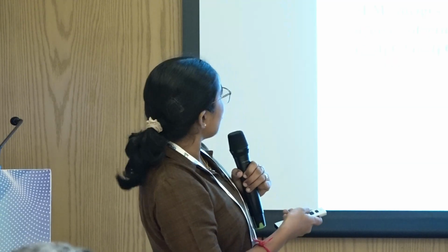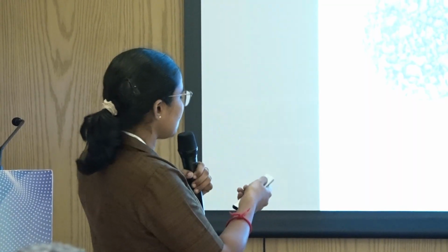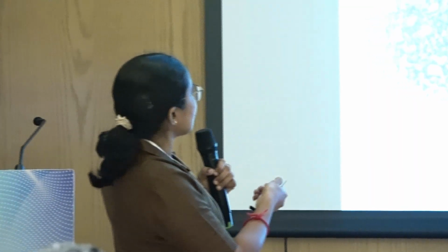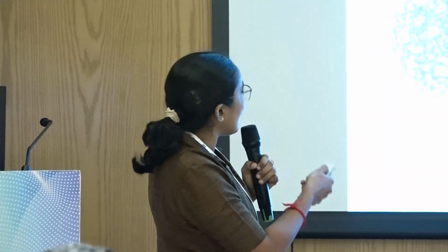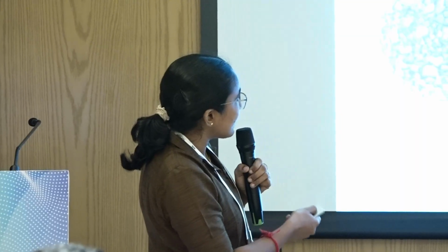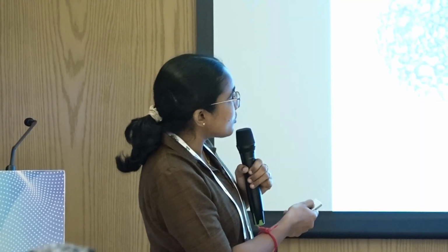And when we observe the same in the X-ray CT analysis, it was observed that in the uncrushed state, the more flaky mica particles tend to occupy a larger space, and they get segregated from the sand particles. So the mica-mica contact was higher, which was influencing the geotechnical properties to a greater extent.